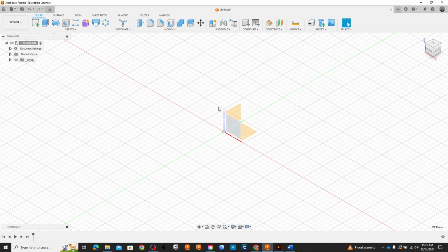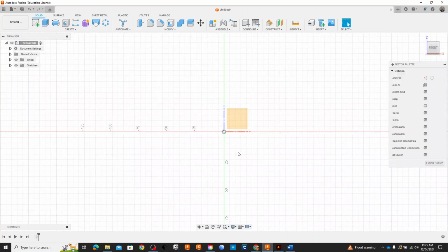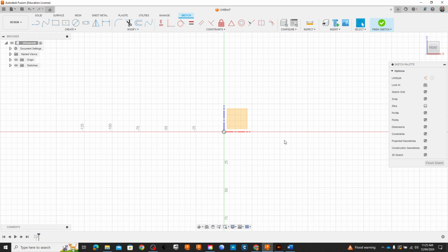Okay. So I'll go through this and I'll go to Sketch up here, hit the Sketch button, and I'll start structuring out what I want to make. The first thing I'm going to do is use this construction line type. So there's solid lines and construction lines. Construction lines you can think of as a scaffold, okay? So I won't be able to model directly from them, but they're there as a guide.